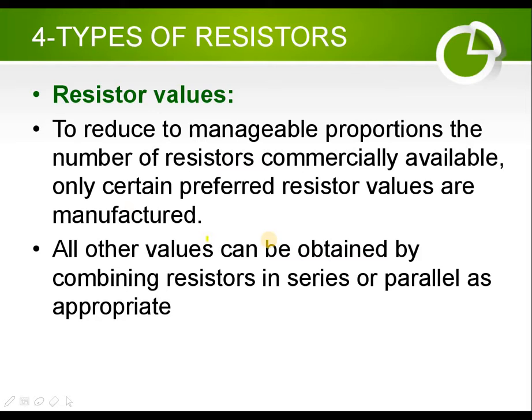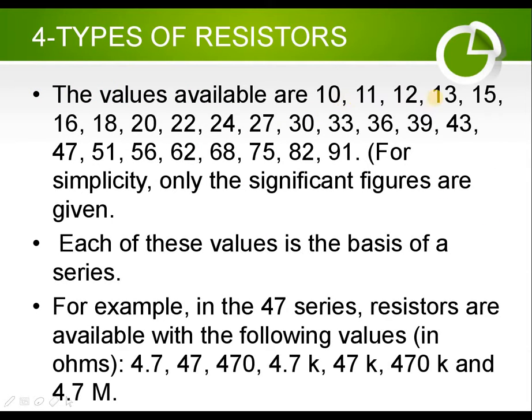And the resistor values: there are different values of resistance commercially available. For example, I write the significant figures right here. You can see, for example, 10, 11, 12, 13, 15, and so on. These are just significant figures I write for simplicity. Other figures are also available, but I want to tell you right here, sometimes if you don't have, for example, a 12 ohm resistance and you have just 10 ohm or